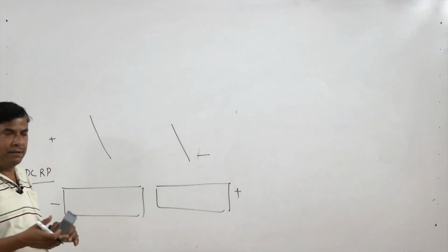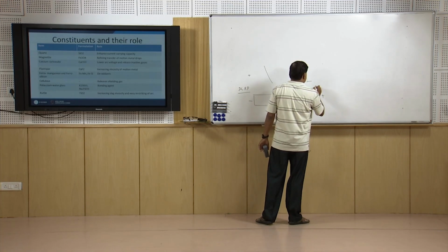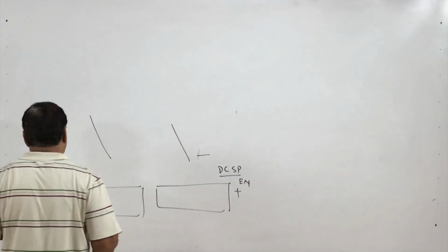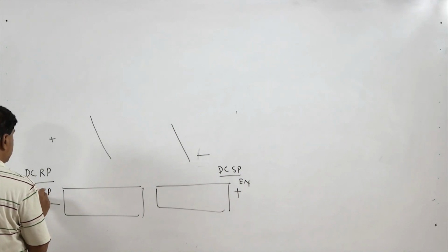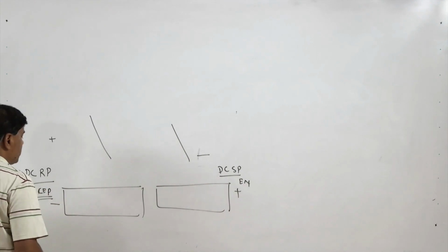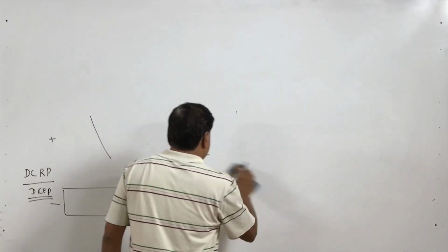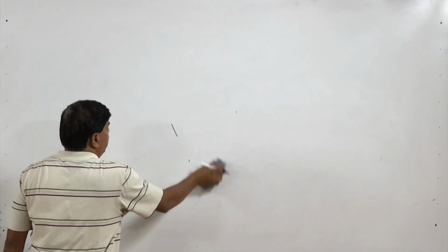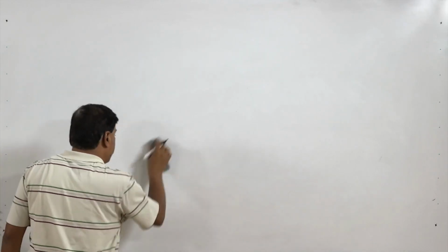So, what is the role of polarity, and when is which type of polarity to be used, that is what we will try to talk about. This is called DC straight polarity or electrode negative, DCEN, and this is electrode positive, DCEP, or the reverse polarity. So, what are the changes associated with this change in polarity during welding, especially in the case of AC, since the polarity keeps on changing? Whatever factors are associated with AC, they will be equally distributed on either side.